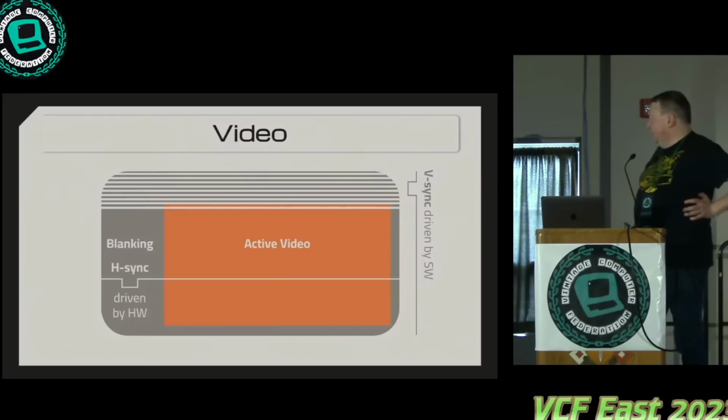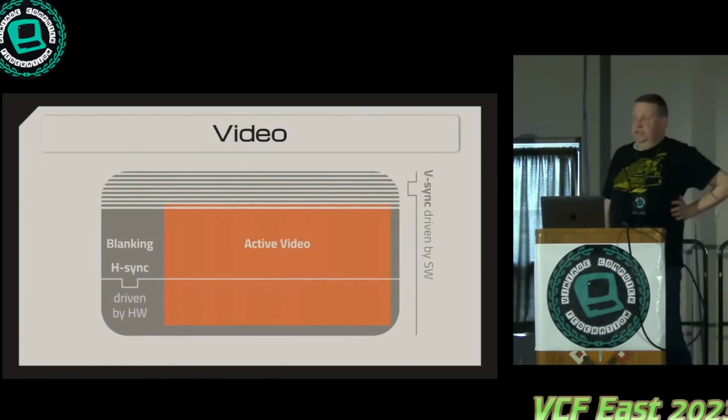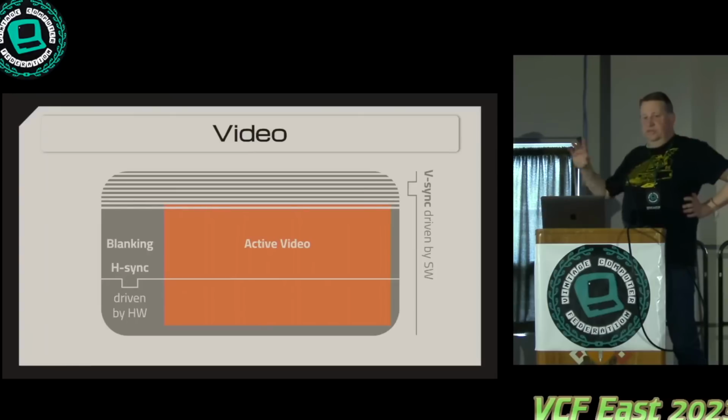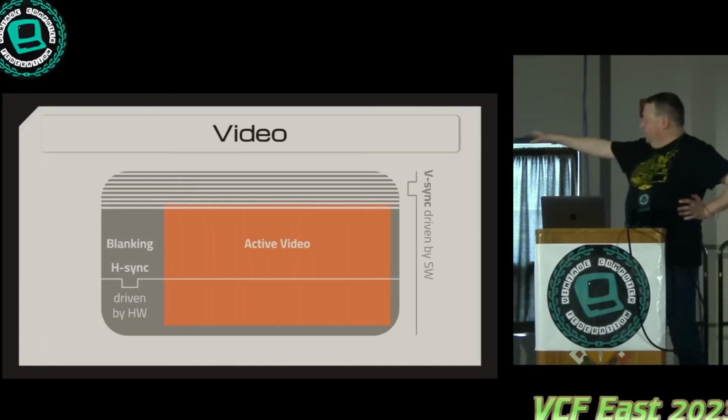So this is the most overhead, really doing the video timing, and this is what's going on in typical VGA-style video timing. You have to fly back at the end of the line. This is the old CRT way of doing things, and then fly back at the end of the page. I show them at the beginning.